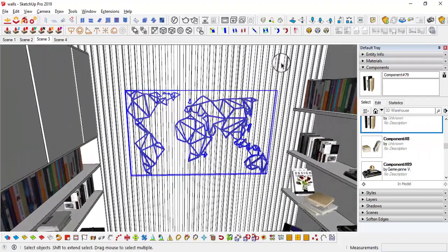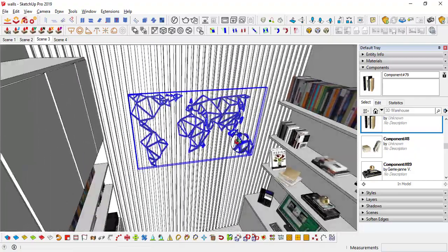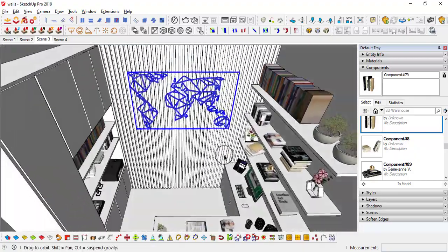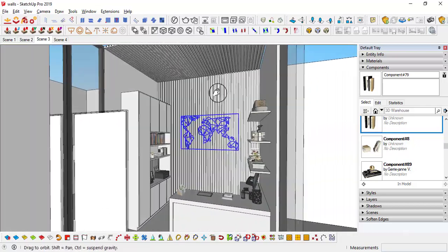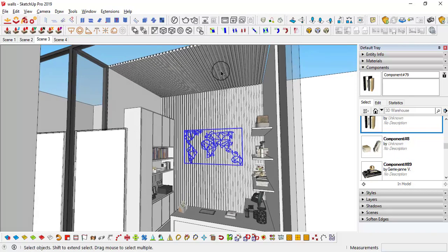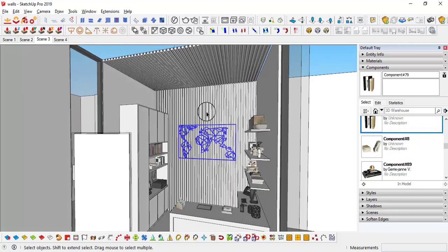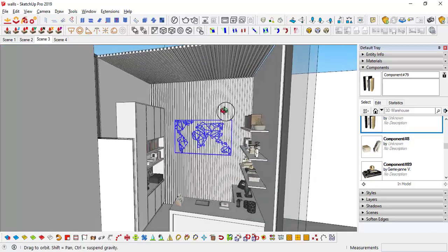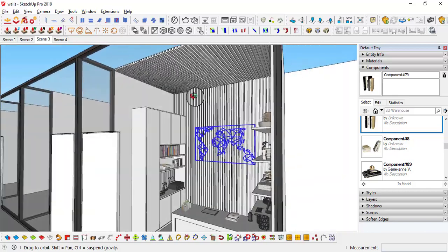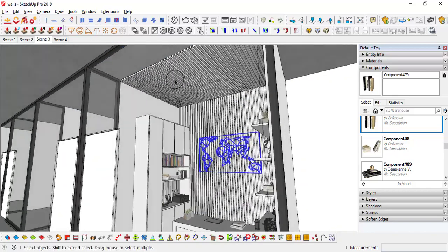What I want to do is make these rafters a black color rafter, and these are like white lighting. So I'm going to use what we call emissive material on this object, and everything is filled up except one thing: we need to make the ceiling. If you observe from the outside, these are like filled up rafters, right? But around 9.5 feet at that height, I'm going to make a hexagonal kind of ceiling, decorative ceilings. Alt H, C, and this is like roof.